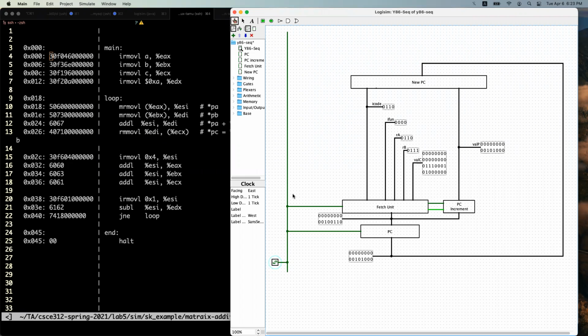And then let's say, to read 6-byte instruction using 8-bit data width, then we need to generate control signal 6 times with different address. Then maybe you can use a counter.